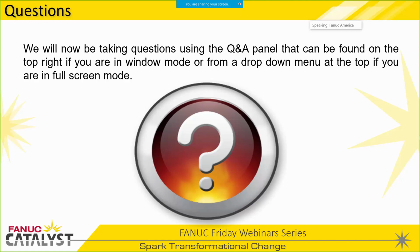And that just looks at a grid from a bunch of different ways and tweaks the mastering from J2 to J5, which will give you a more accurate robot, because J1 and J6, when it comes to absolute accuracy, are redundant, don't matter. So there's stuff you can do on your own with vision mastering. There is signature analysis, which can be done here. And I believe you can even order some of those units from the factory already signature analyzed. So just work with your FANUC salesperson to figure out if the model you're interested in supports that or